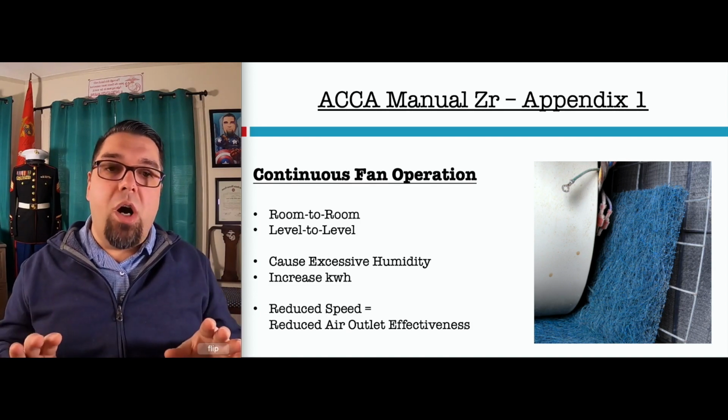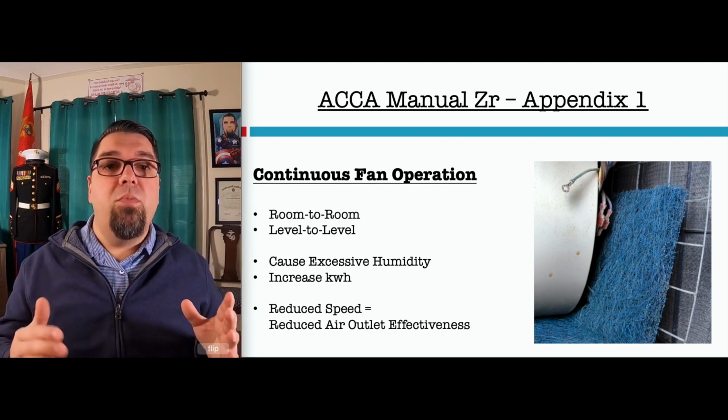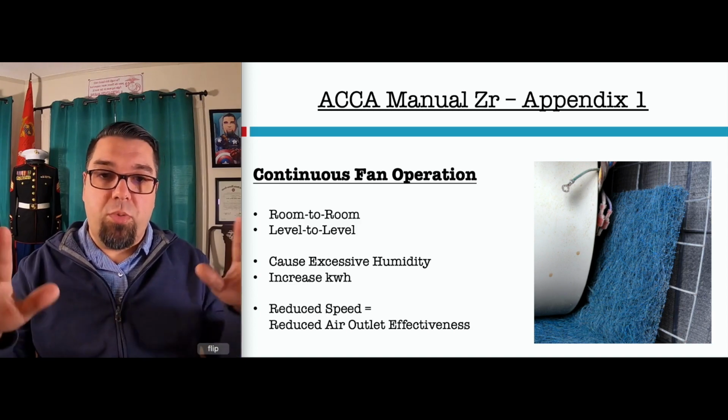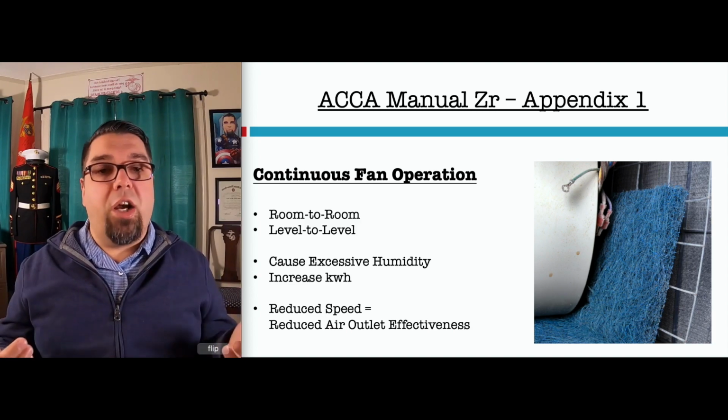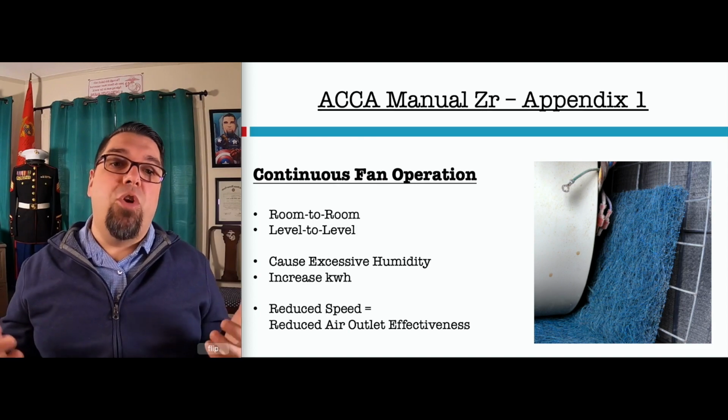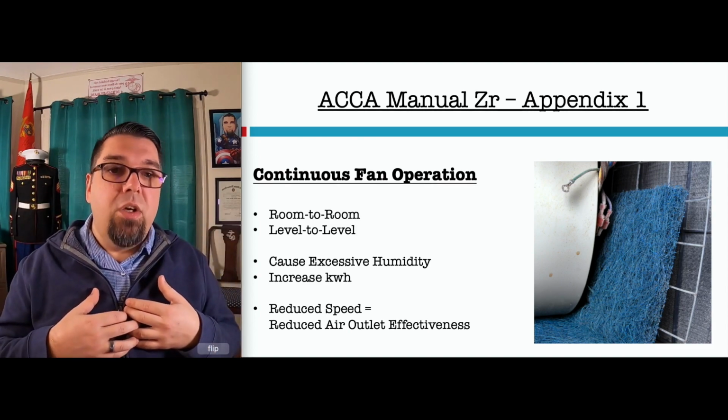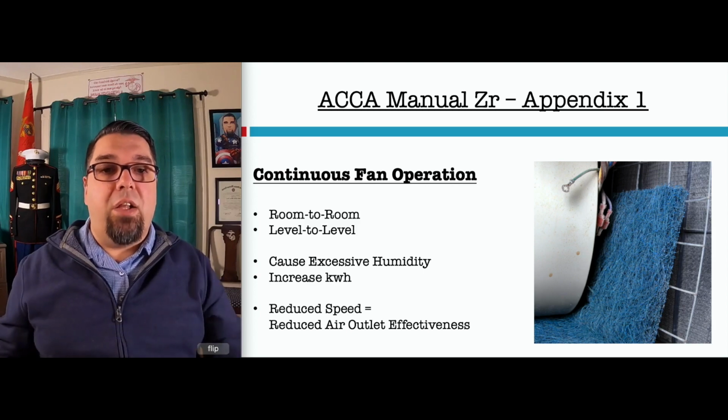Now, don't get me wrong, heat does go from hot to cold, and you might not have a big temperature difference across those rooms when you turn the fan speed way down, but you're certainly not gonna be mixing the air in that space. And if you're not gonna be pulling air back from that space, that's when you start feeling that radiant heat loss and heat gain.